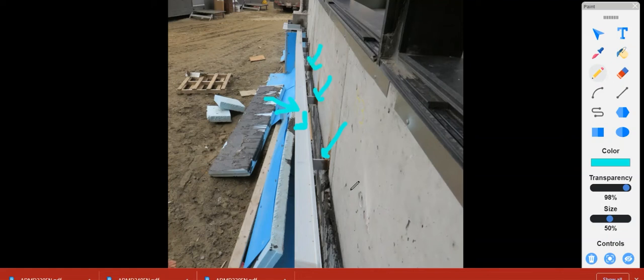And what this does is, rather than taking the angle all the way back right against the concrete like that, which would be a continuous piece of steel going through the insulation plane, which will be on the outside of this building, by pushing the angle off and just doing that, you can now get insulation in behind the angle, and the only thermal bridging you have is at the actual knife plates there.